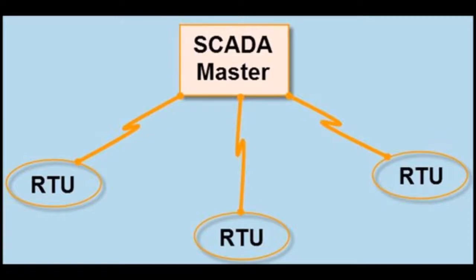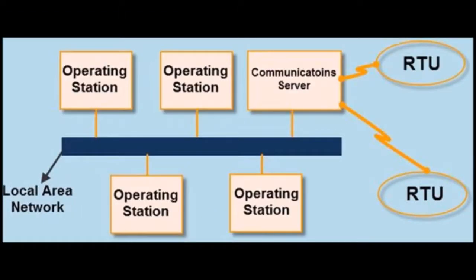The second generation is called distributed SCADA system. In the second generation, the sharing of control function is distributed across multiple systems connected to each other using a local area network. Hence, these were termed distributed SCADA systems. These individual stations were used to share real-time information and command processing for performing control tasks to trip the alarm levels of possible problems.